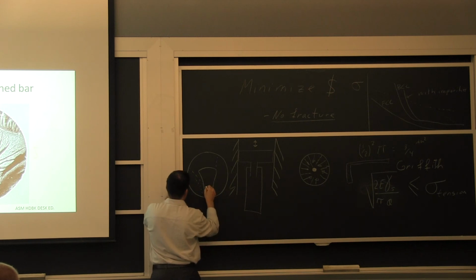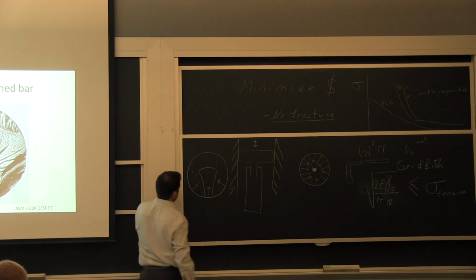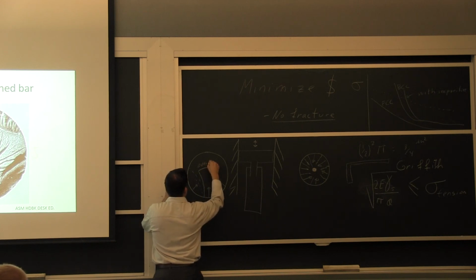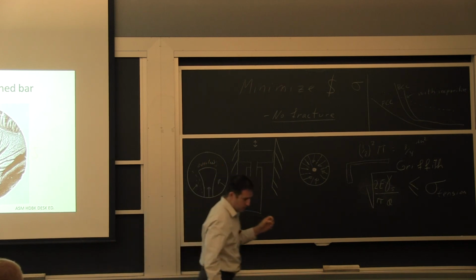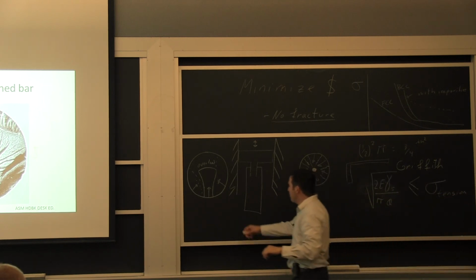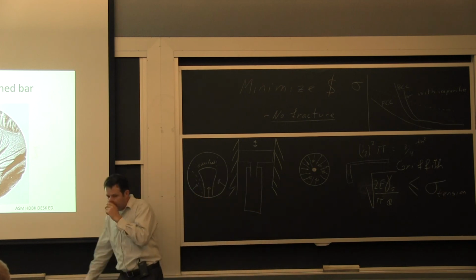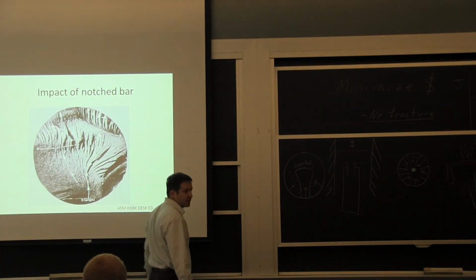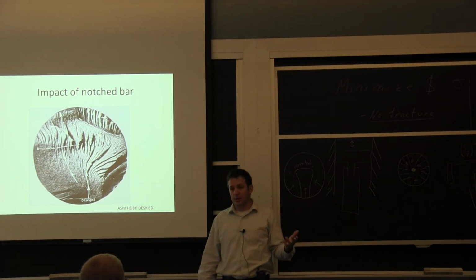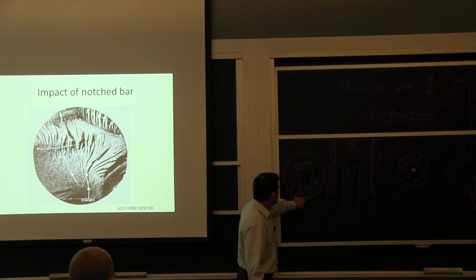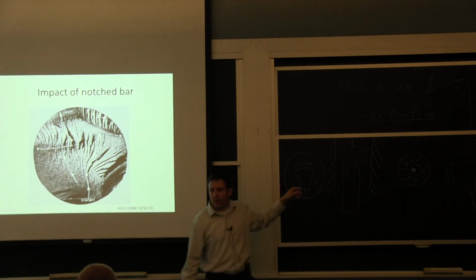So I'm almost giving you the answer here, but that's fine because we don't have the time. It's not a fracture class. And the overload is here. There you go. So it's another example. There were three main initiating cracks. Over here, it's easier. We just have one origin, and it just keeps going to the other side, and there was bending load. The example I'm giving you there is more of a tension because the crack started at a different location around and went to the center.